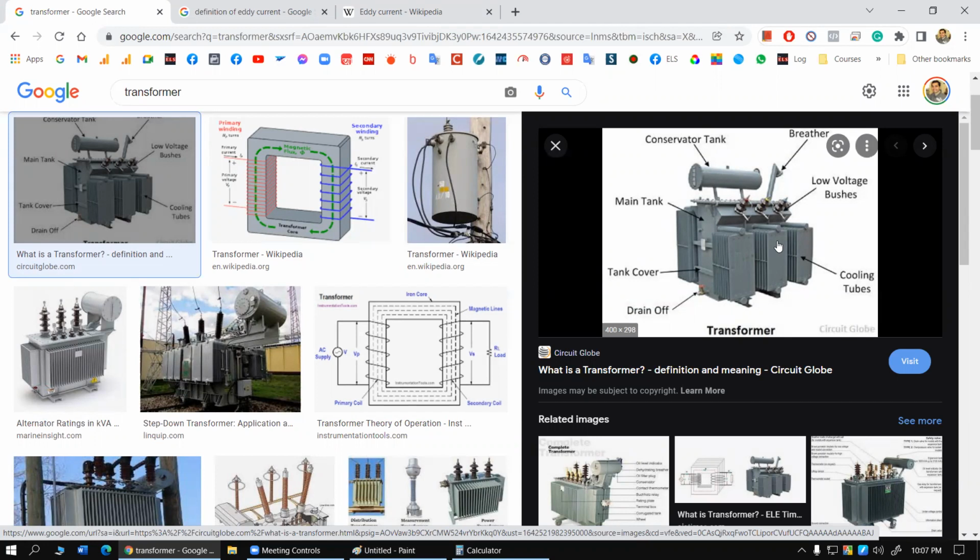Now, whenever the oil becomes old enough, sometimes it dissociates and produces particulate carbon, which can clog up these pathways, and the convection current cannot happen as much as it should for effective cooling. That way the transformer can slowly start to heat up, and at one point, if it cannot handle that pressure, it goes off, boom. It actually doesn't produce an explosion, it simply disconnects the circuit and stops the current.